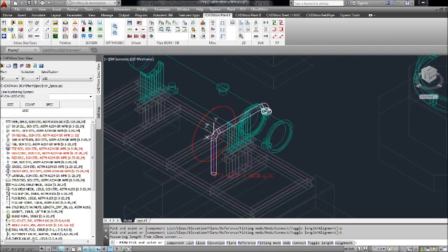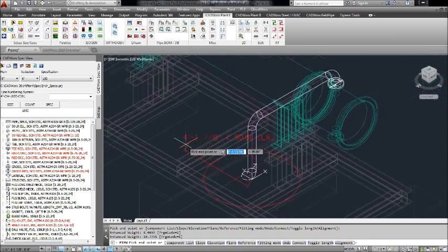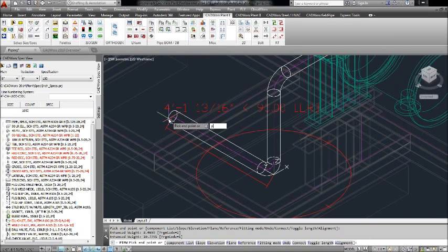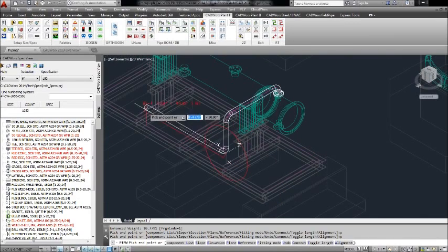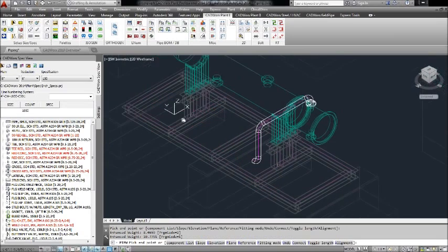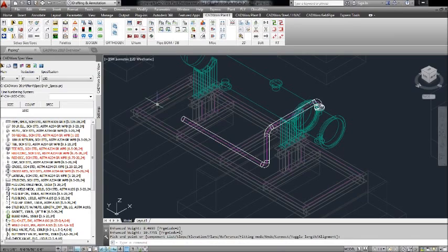And what I'm going to do in this case, I'm going to pull down and go an arbitrary length. I'm just going to click here because we're going to use some nice automation in a little bit to set the elevation for the bottom of this, what will be a little control loop here. And I've started to change from my elevation change, and I'm running north this time. I'm going to again hit P and Enter because I want my compass to be up in the correct plane of operation. Okay, and now again I'm going to pull out north, and I'm going to click just an arbitrary length because again we're going to use some nice functionality from our new grip system to determine the length and the layout for this run.